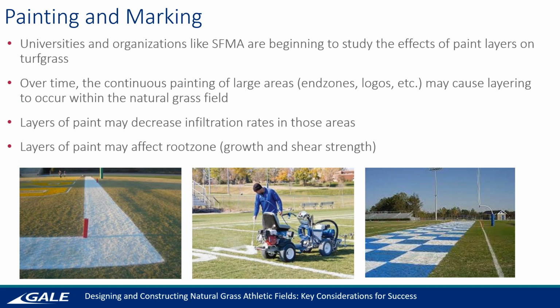So what they're finding, and several universities are trying to do a little bit more tests, and the Sports Field Management Association is looking into it a little bit more, is whether it's the chalk or the temporary paint that you're doing, the layers that are going there are now over time going to the full depth of the growth media. So that's affecting the way the area that's being painted drains. So you're getting much lower infiltration rates in that area.